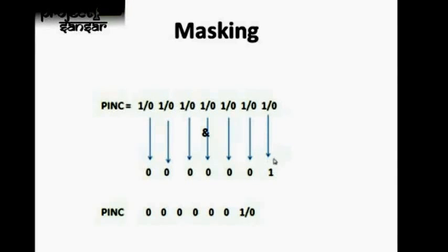For example, I am interested in reading the value from pin 0 of port C. Then I am not concerned about the inputs of the rest of the pins. So I want to isolate pin 0 from the rest of it. What I do is I AND the rest of the pins with 0, so they will always give me a value 0 for all other pins.